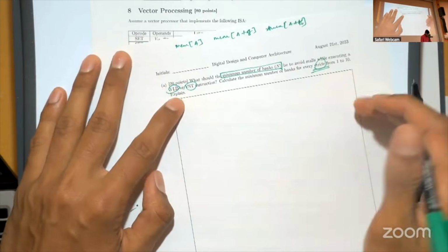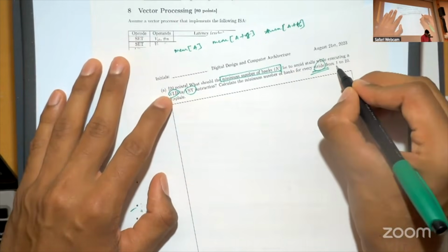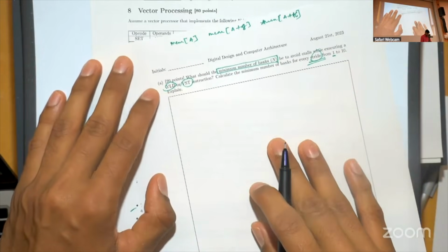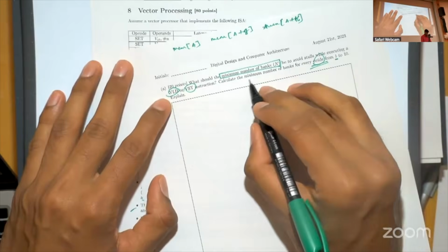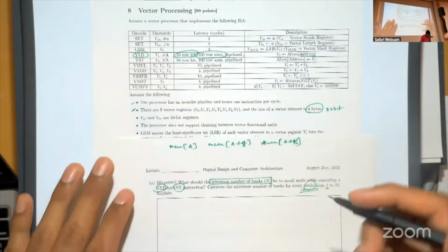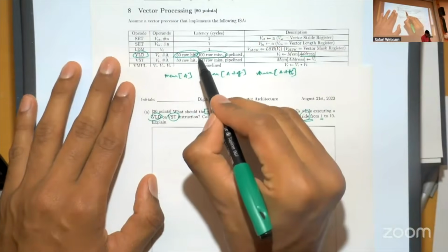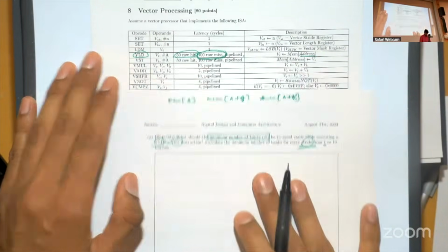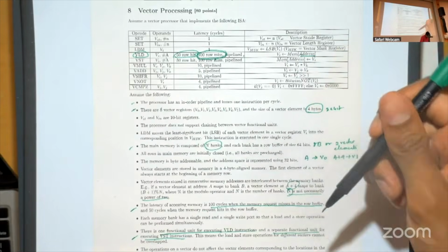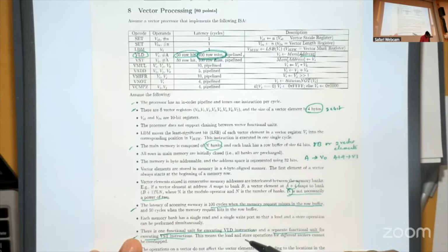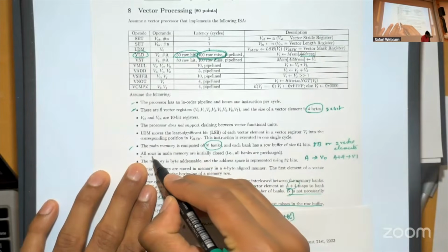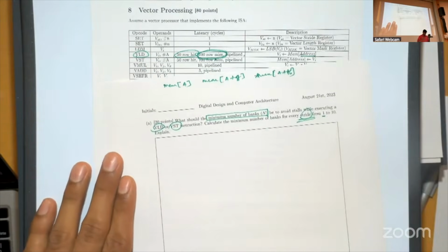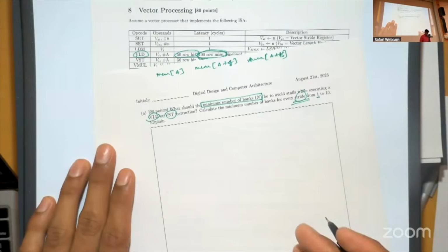And what you can think of here is to start with 1, 2, 3, 4, 5, 6, 7, 8. Assume different strides and think about how many banks you would need. We know that this is the penalty that you pay on a row miss. And why we should consider the row miss penalty is because they describe that the DRAM is first entirely closed. All rows in the main memory are initially closed. So the first access is always going to be a row miss.